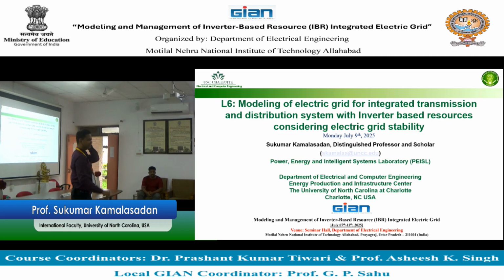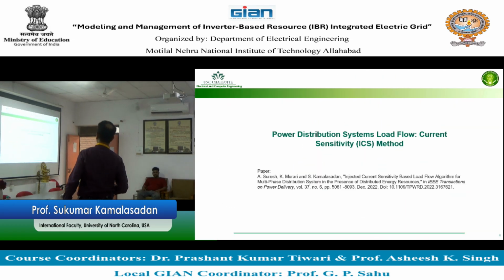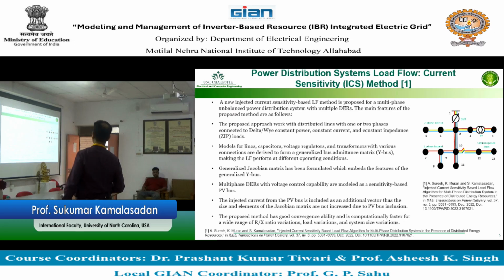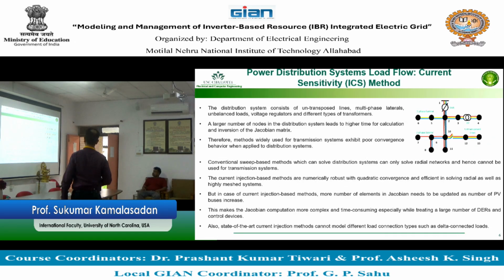So then we discussed, okay, we have a voltage regulator motor controller we can include. Can I include any other controller which is slow moving? Yes, any slow moving controllers can be added into the quasi steady state time series power flow. For example, a battery pushing power based on set points, slow. You can include that. So having said that, we looked at the quasi steady state time series power flow.